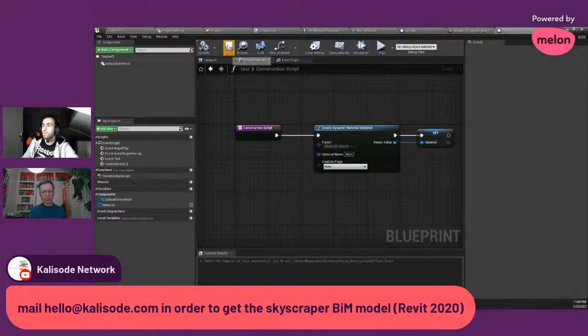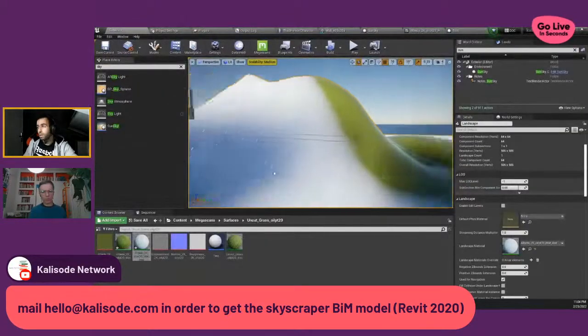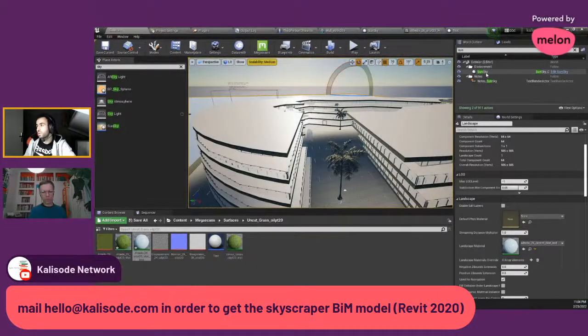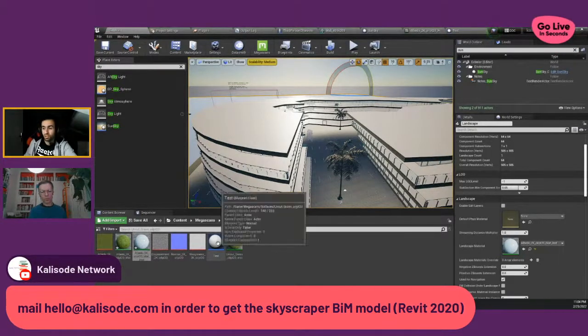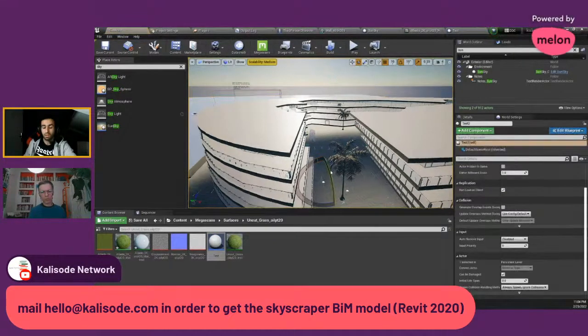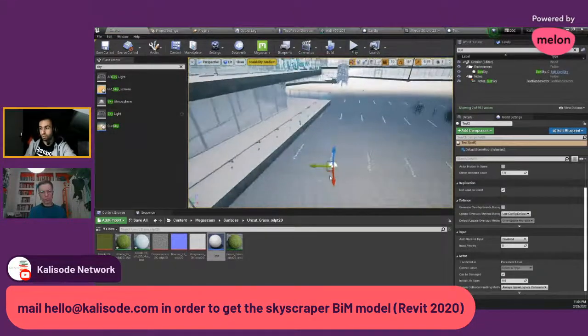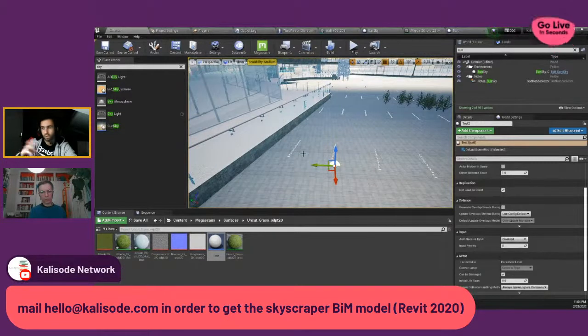Okay. So as I told you about the actor that Epic Games has created for you, for Revit users, when you create some actor, you can just drag and drop it into the scene. If the actor contains a mesh or anything like that, you have to be careful about its position. You have to set the position accordingly.